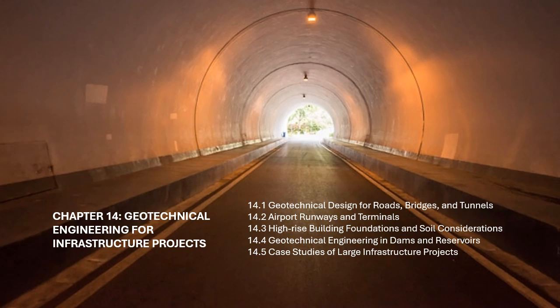bedrock. Pile foundations are often used for bridges over water bodies or in areas with deep soft soils, whereas spread footings or drilled shafts may be suitable in areas with competent bearing strata near the surface. Soil structure interaction, SSI. Geotechnical engineers must evaluate the soil structure interaction to ensure that the bridge's foundations respond appropriately to applied loads and settlement.